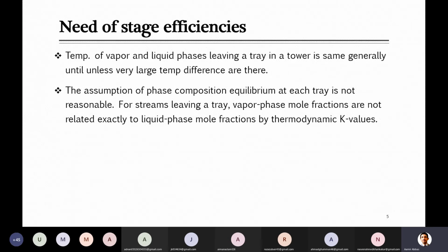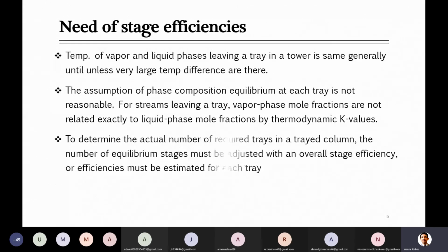That is not achieved 100%, it will be less, although some component will be transferred from vapor to liquid or liquid to vapor. I am saying this in the case of an absorber, for example, where you want to absorb some component from gas into liquid. The transfer you expected on any plate is not done 100%, because in reality they don't reach equilibrium completely. Yes, partially they can reach it, but not completely.